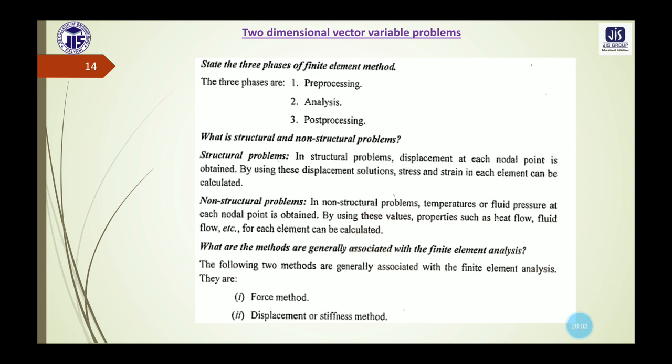Our next question is, what is structural and non-structural problem? So the finite element method or finite element modeling that we have discussed earlier, there we have seen the classification of these finite element problems, these are actually structural and non-structural problems. And in case of the structural problems, we actually focus or we actually calculate the displacement at each nodal point, and by using these displacement solutions, stress and strain in each element can be calculated.